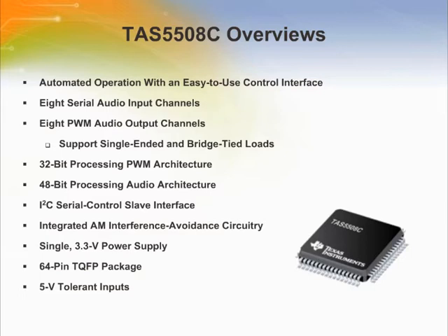The TAS5508C can drive 8 channels of H-bridge power stages. It supports both single-ended and bridge-tied load configurations. The TAS5508C also provides a high-performance differential output to drive an external differential input analog headphone amplifier.